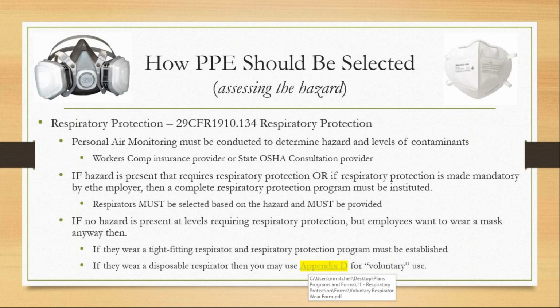They'll look at the SDSs for the stuff that the people are using right there. They'll take those SDSs and look for threshold limit values and exposure limits for different chemicals that are in there. And then they will select the proper cassette to draw air through to test for those chemicals.